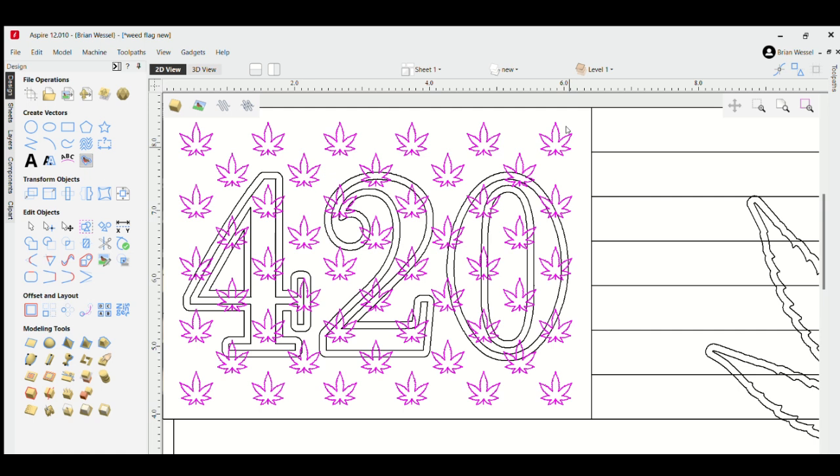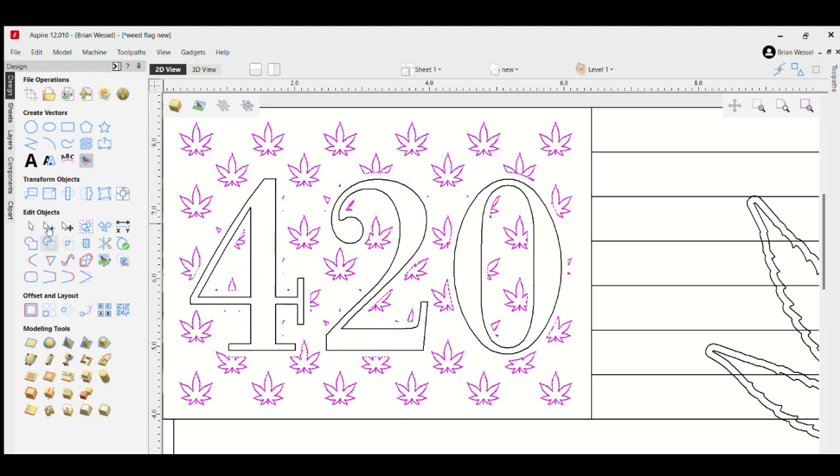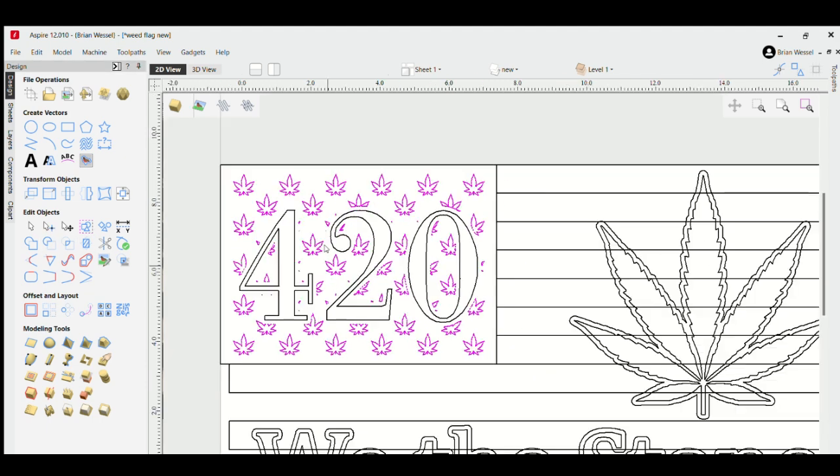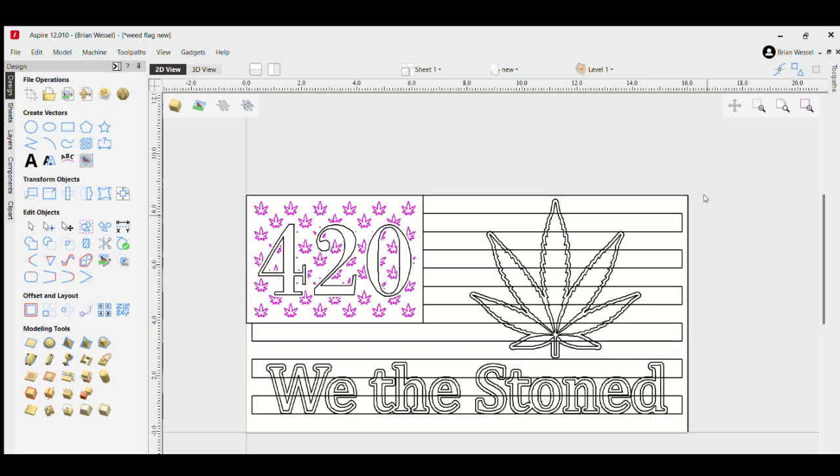Now, whenever you click on one of those, you have all of them. We're going to click on that, and we're going to click on the offset line, shift and click, and there's a weld button right here. There's a weld and then a subtract button. Subtract second selected vectors from first. You do that, you're left with the 420. Now we're going to use that same button. Oh, I almost forgot. Before you click off of it, it's easier. You shift.